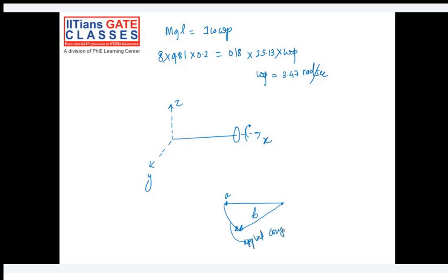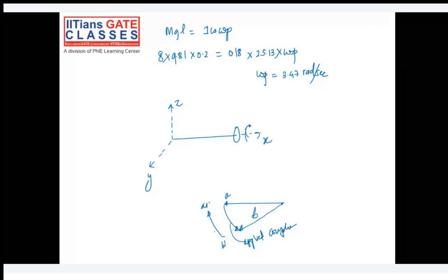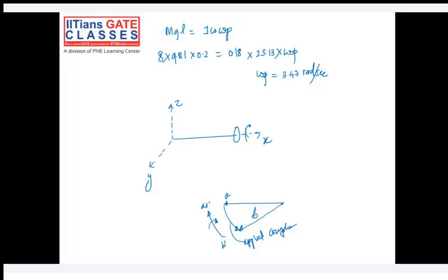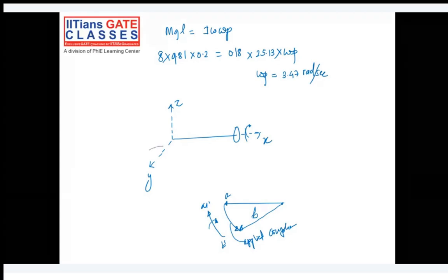So here this will be your gyroscopic couple B dash A dash. B dash A dash is a reaction couple, which is clockwise, because you can clearly see this. Use the right hand thumb rule. It is clockwise here, not counterclockwise, and it tends to give the arm a clockwise rotation about the y-axis. So try to imagine. It will try to give a clockwise motion about the y-axis. So this is what is happening here.